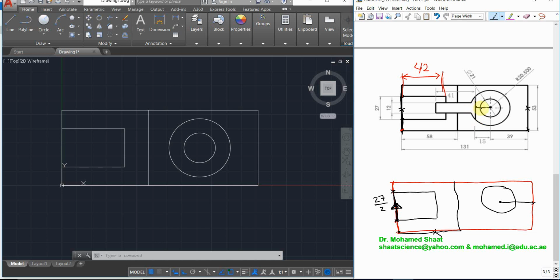So I'm going to draw a line from the center point with a length of 15 millimeter. The end point gives me the midpoint of this vertical line. Then from this midpoint, I'm going to draw any line with any length going down. Any two lines, one vertical up, one vertical down, with any length. Make sure that these lines go outside the circle on both sides. Then I can use trim to cut these extra portions. Make sense? This is basically what I'm going to do.